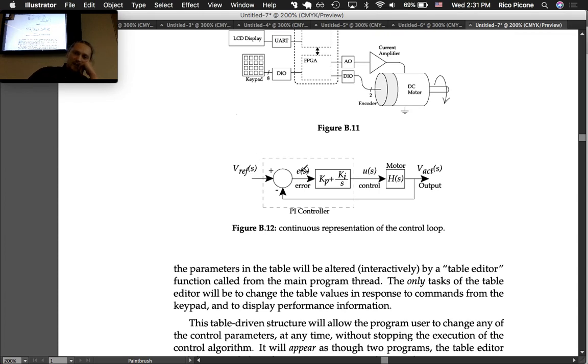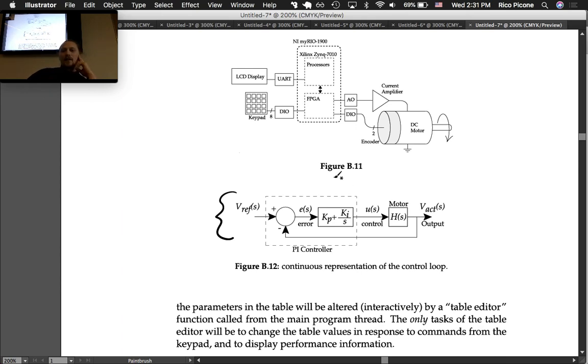So this is our control law. This is like the basic block diagram of the control loop. We're gonna get into a more detailed one at the end of the lecture, but this one gives you an idea of how this works. So you have the motor that has some actual velocity that is going to be measured through, I guess you could think of it as being a voltage. It gets fed back and compared to what the velocity should be in terms of the voltage that it represents. And those details will be worked out in the other block diagram.